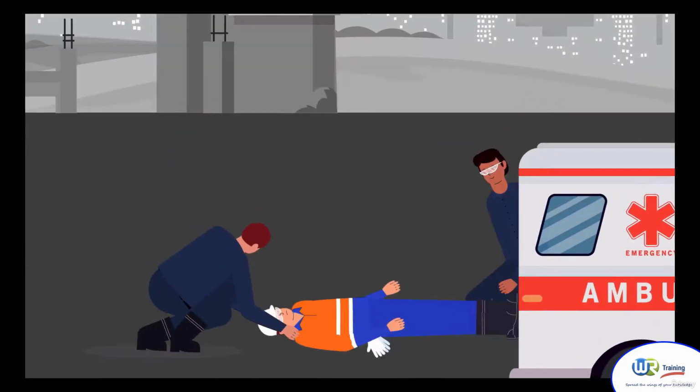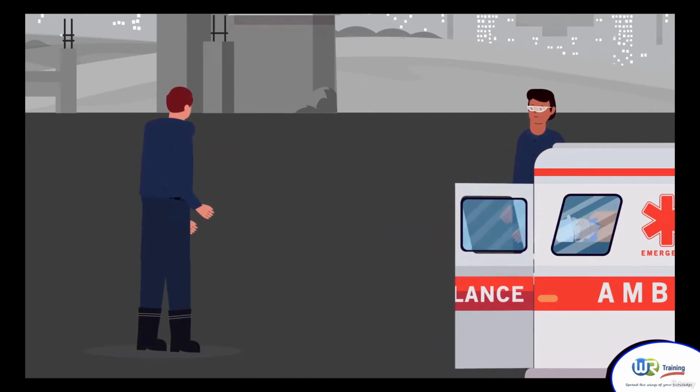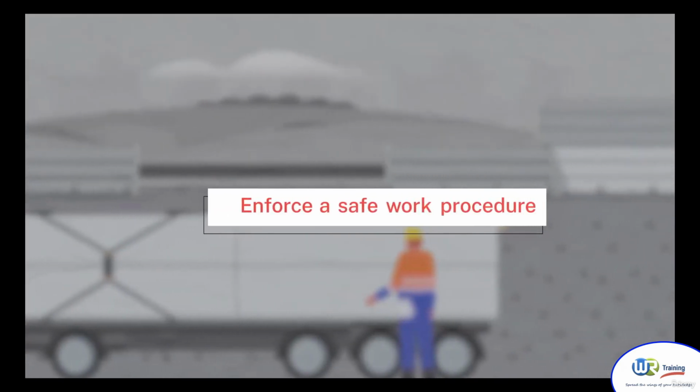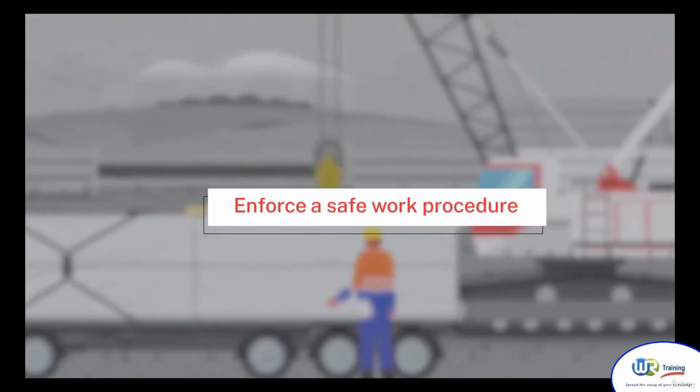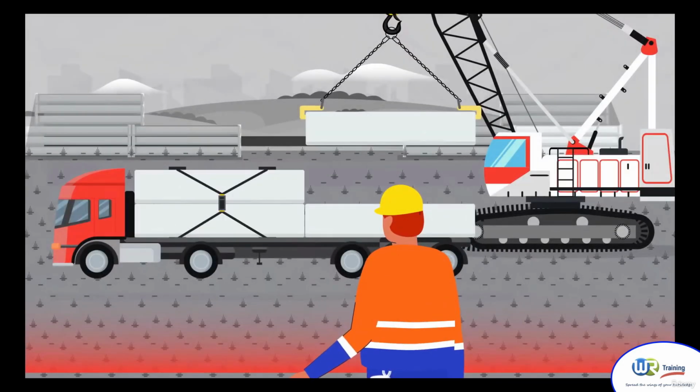The truck driver was struck with the end of the casing, trapping him between the suspended load and another casing on the truck. He sustained serious crush injuries, requiring hospitalization. An investigation into the incident identified that the piling company failed to enforce a safe work procedure for loading and unloading objects from trucks, including enforcement of an adequate exclusion zone around trucks during unloading operations, enforcing a requirement that non-essential personnel, such as the truck driver, remained outside of the exclusion zone at all times.